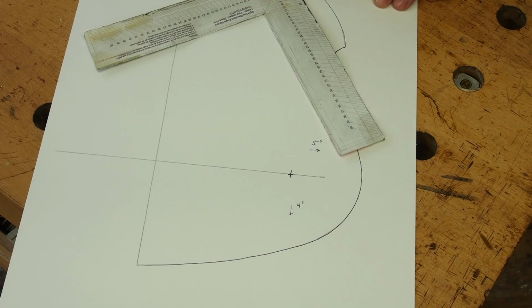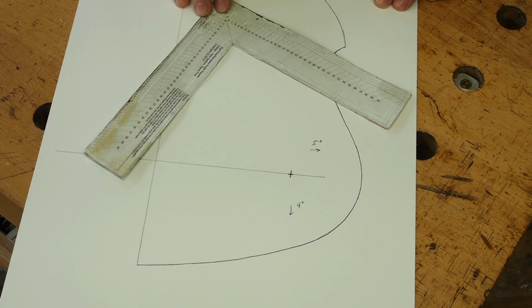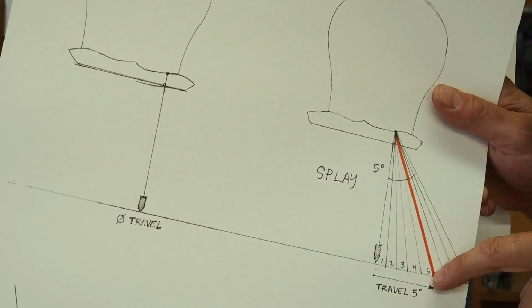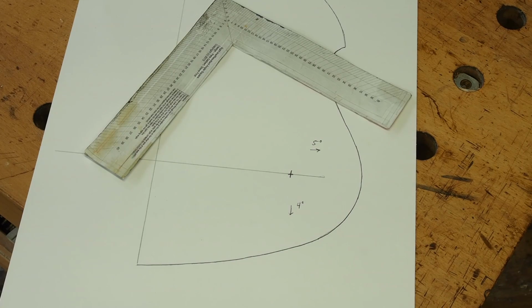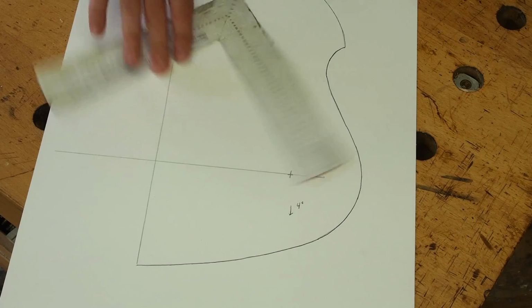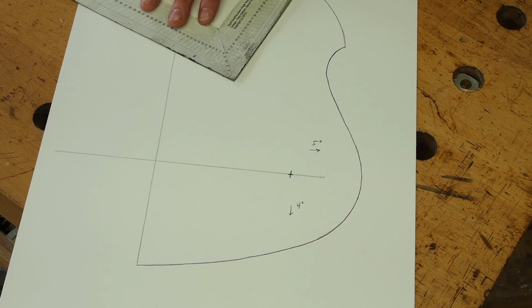But there's actually a really easy way that I've got for laying this out. So when I'm working in the most practical manner, just trying to do my job here, I've got this rule here that I've made. This is what I call a sight line rule, or you could think of it as a travel rule. Basically, it's just the bottom portion of that scale that you saw before, because it counts off angles as a distance along the floor plane. So what I'm going to do is I'm going to come down here and show you exactly how I would lay out 4 and 5 for my rake and my splay to get my resultant and my sight line.